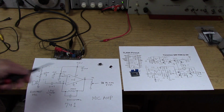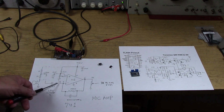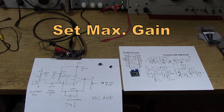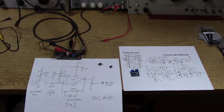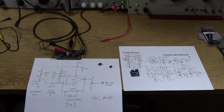So, with a microphone amplifier like this, we need to have some gain, but not too much. So I'm going to start with a 1K resistor on the inverting input and a 100K feedback resistor. So that's a gain of 100. Log of 100 is 2, times 20 would give a gain of 40 dB. Now, I'm not sure if we're approaching 40 dB, but that's the amount of gain that the op-amp is supposed to give you, probably in the middle of the audio range.